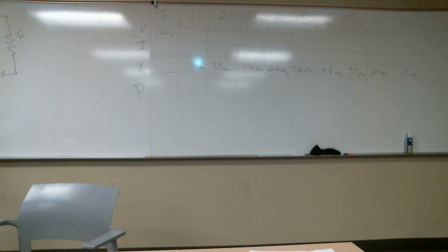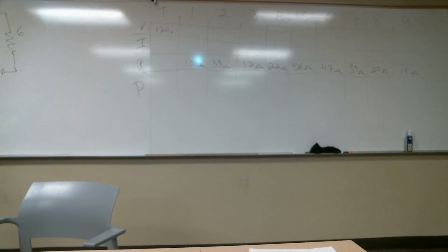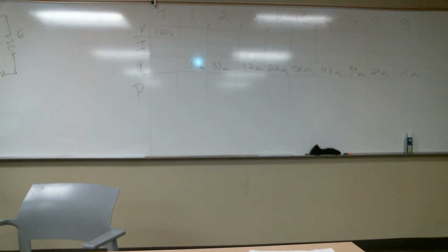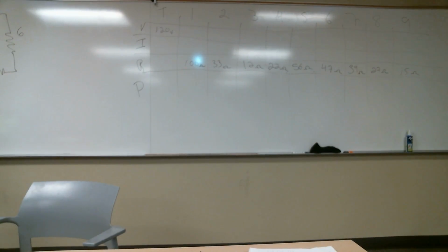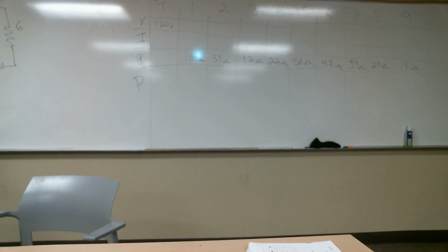So, with respect to doing the series parallel analysis, the first rule, any place we can combine parallels or combine series without doing series parallel. Does that exist here? Can we do any parallels? Doesn't look like there's any parallel branches that are pure parallel on their own. But it does seem like there are 3 series loads in series all on their own without any parallel in between them, right? Seems like 3, 6, and 7 could be combined into one value. Okay with that? So 3 is 12, 6 is 47, so that's 59, and 7, 59 and 39 is going to be 98.